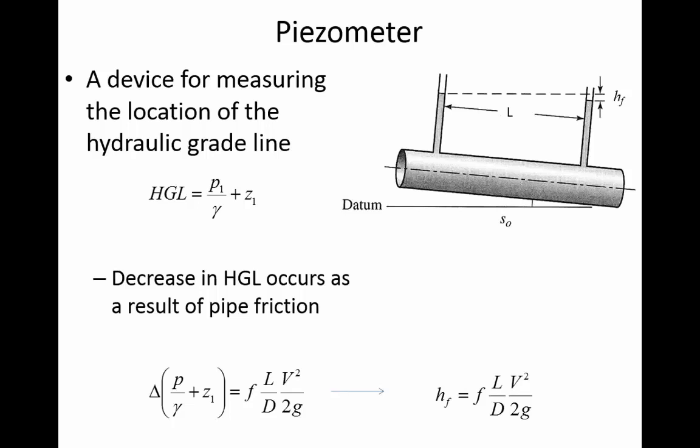Diameter of the pipe is in the denominator, meaning that if you have a small pipe, what effect is that going to have on the energy loss? It's going to have a lot of energy loss, actually for 2 reasons. Because a smaller pipe is going to increase the velocity, so that's the indirect effect of the small pipe. But directly, when you have a small pipe, think about how far away you are from where the resistance is.